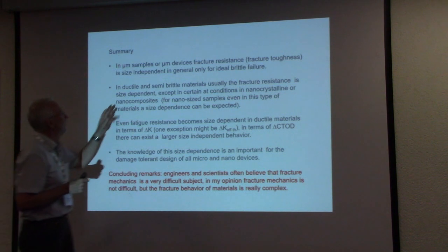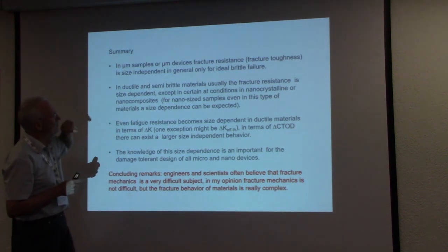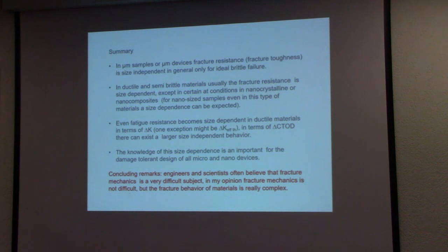For ductile and semi-brittle material, the fracture resistance becomes size dependent. And this size dependence is really important and not really well examined. There exist no rules for that, and I think in the next few years they will develop some simplified estimation of fracture resistance as a function of the sample size.